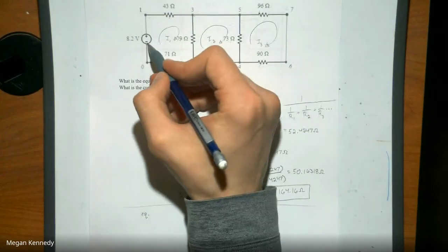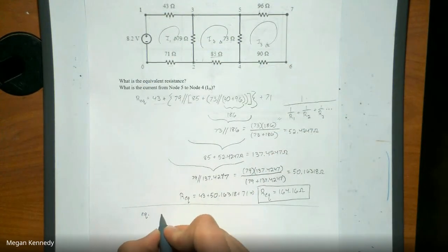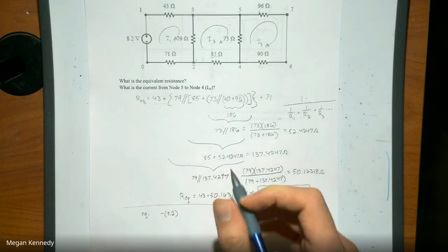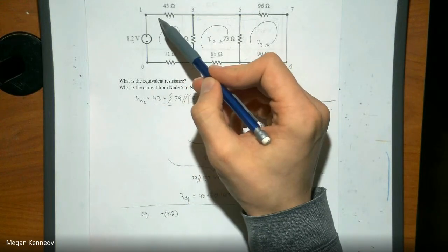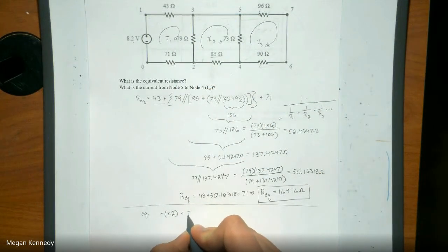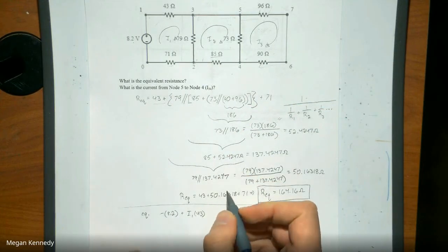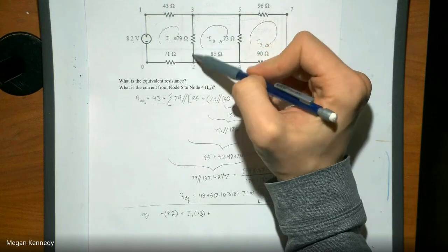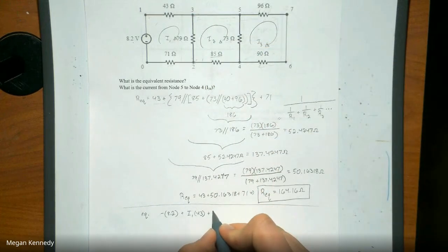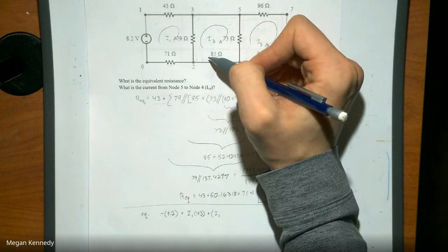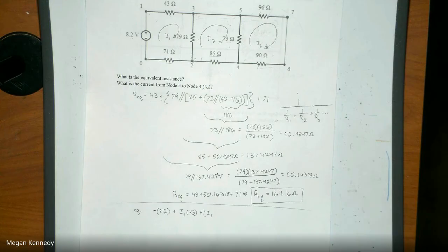So in this case, we have the negative side of this voltage source. So we have minus the value of the voltage source, 8.2 volts. As we keep going, now we have the voltage drop across this resistor to account for it. So that's plus I1 times the resistance, 43. Plus, as we keep going around, we want the voltage drop across this resistor right here, and that is equal to I1, our current flowing down, minus the current that's flowing the other way, as we have described it.